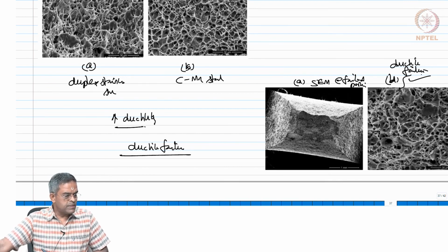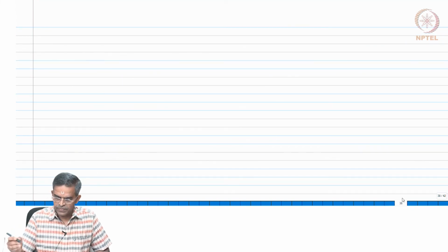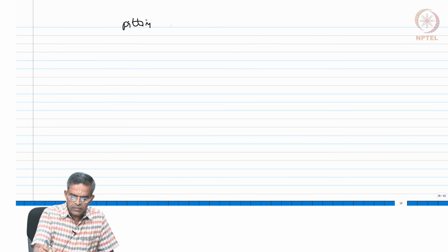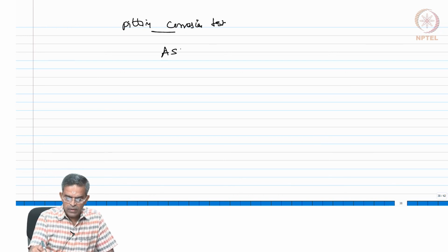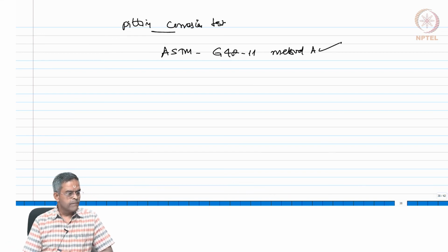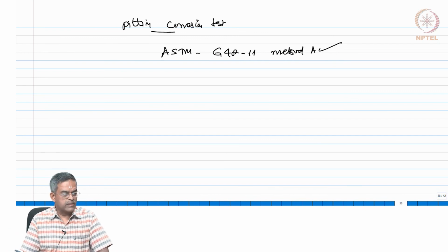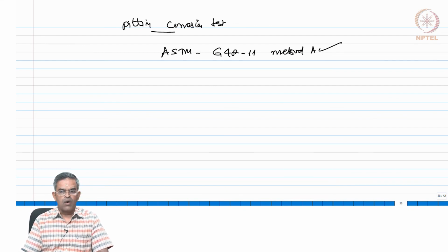Furthermore, a pitting corrosion test was also conducted on the build using ASTM G48 method A. The test solution used is about 100 grams of reagent grade ferric chloride in 900 ml of distilled water. All the surfaces of the mold were ground clean using 120 grade emery paper.